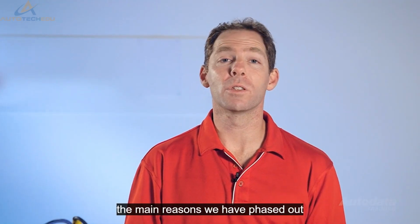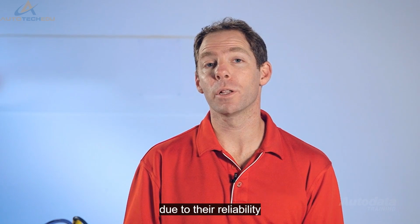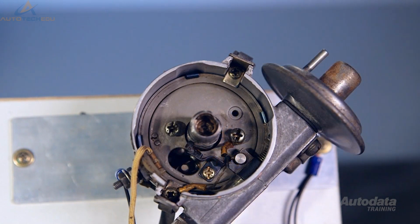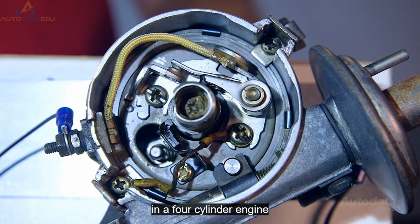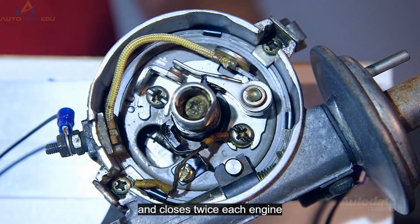One of the main reasons we have phased out contact breaker ignition systems is due to their reliability. A contact set, being a mechanical device, is subject to wear and tear. They use a distributor cam to open and are closed via a spring, manufactured as part of the contact assembly. In a 4-cylinder engine, a contact set opens and closes twice each engine revolution.